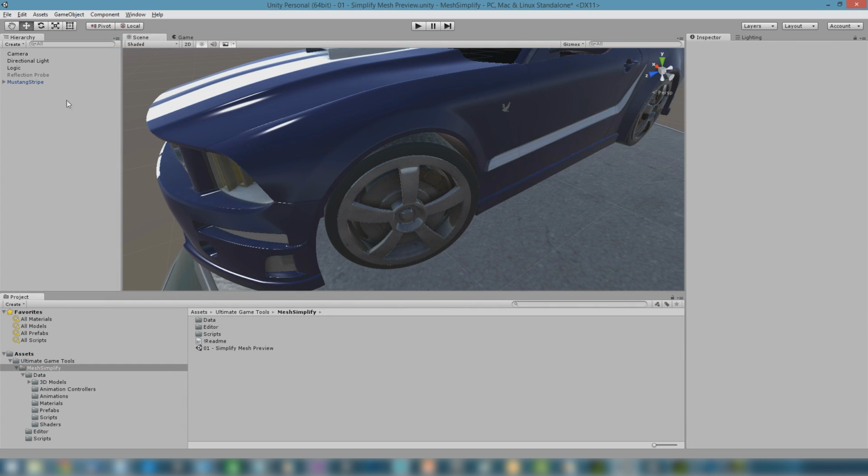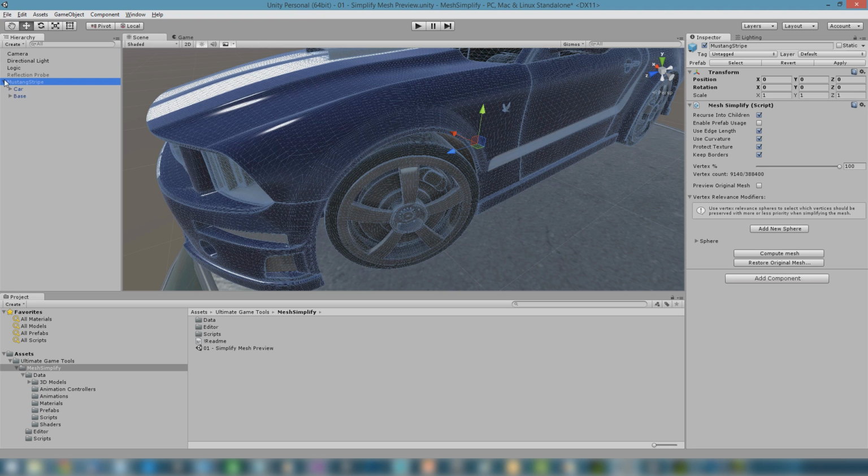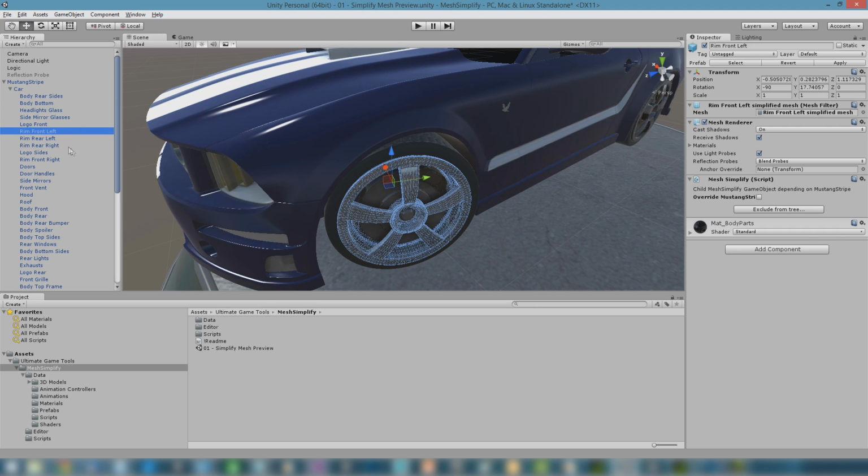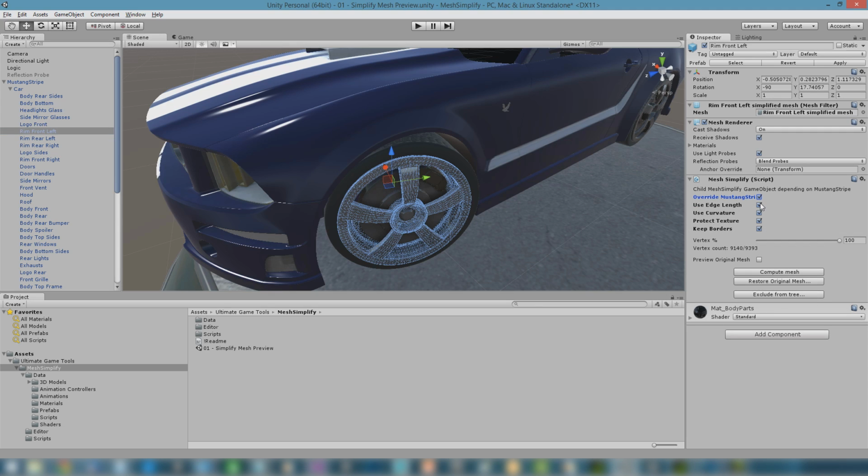In object hierarchies, we see child nodes have a different Mesh Simplify panel. Since the root object controls all parameters, it doesn't give us any control by default. Sometimes we want to apply different simplification settings to a child object. We can do this by checking the Override Settings parameter. This opens a new panel where now the child object can also be configured.